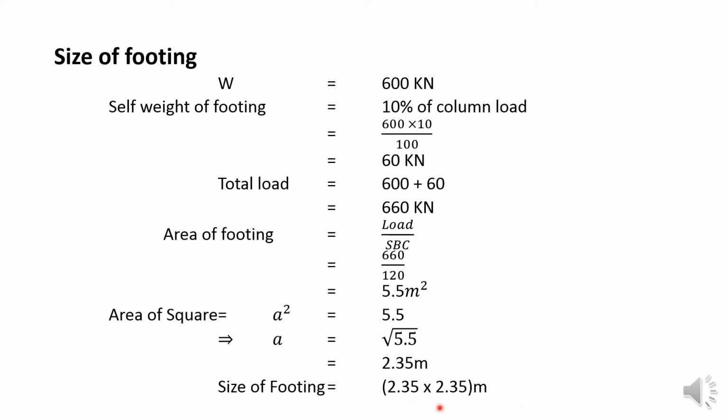That is the size we have to find out using this load. We just increase the load by 10%, and from that loading condition we have to find out the size of the footing. So finally we fix the size as 2.35 into 2.35 meter.